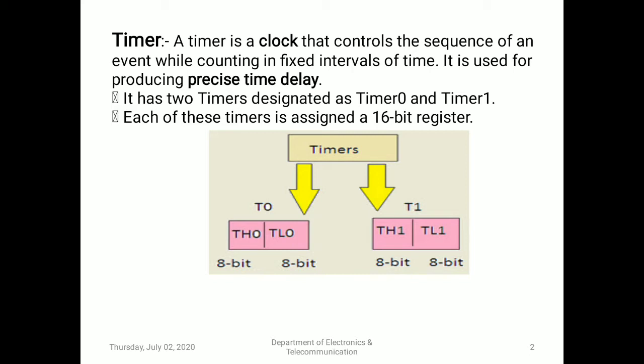If we are connecting a device which changes its state, and suppose 10 millisecond time is required to change the state, on to off or open to close, like relays, and if you are triggering that relay in less than 10 milliseconds, that is 1 millisecond or 500 microseconds, that is 0.5 millisecond, in that case you won't get the switching between on and off or open and close.